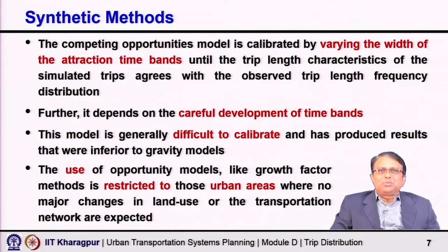The use of opportunity models like the growth factor method is restricted to those urban areas where no major change in land use or transportation networks is expected. That is the key. Both cases, this model as well as growth factor based models, have restricted applications where no major change in land use or transport network is expected.